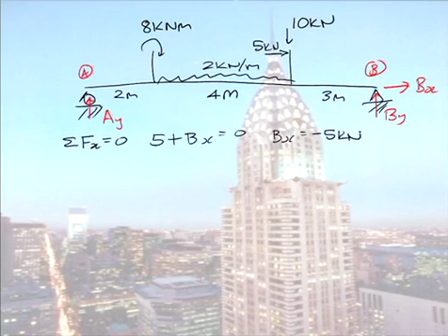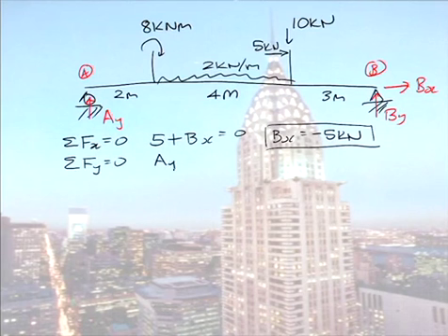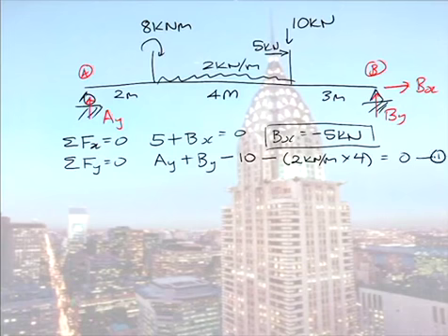In doing this question, this will probably save me looking at the first question on the test paper. So we have one of our unknowns. We have 3 unknowns, 3 equations of equilibrium, so we can solve. If you then move on to your forces in the y direction, which is usually the next way we go, you would say, okay, I have my 2 unknown reactions. I have my minus my point load 10, and then I have my UDL load of 2 kilonewtons per metre acting over 4 metres, and all of that equals 0. So that won't actually tell me what either A or B equal. So now I need to take moments.